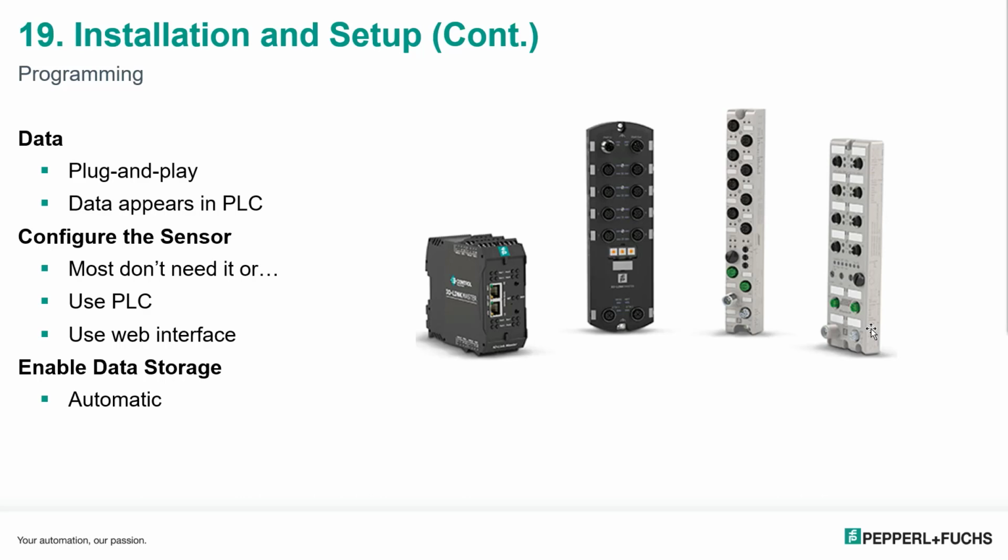But what you might have to do is configure the sensor. Maybe you have to put an on or off delay in, or configure an LED pattern for a light or something like that. So get your configuration done for your IO-Link device. Maybe that's done on a web interface. Maybe that's done in the PLC. Maybe that's done secondarily with a USB IO-Link master. Just get your device configured the way you want it.